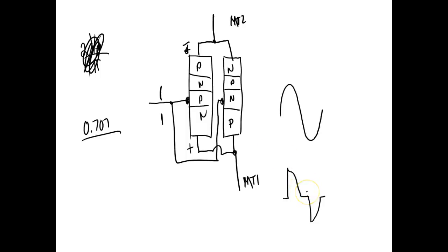Now, if you've got a regular meter and you look at the output of a triac, it's not going to give you the right voltage unless it's passing the entire waveform. A true RMS meter would. Now it's going to show less, but it's not going to read what you're actually getting across your load. So we can use these things on resistive loads.